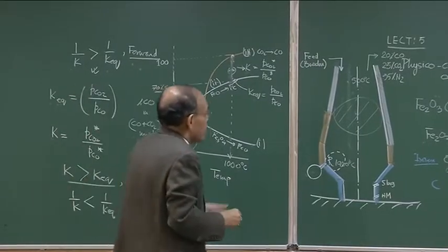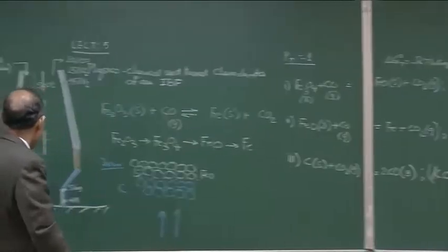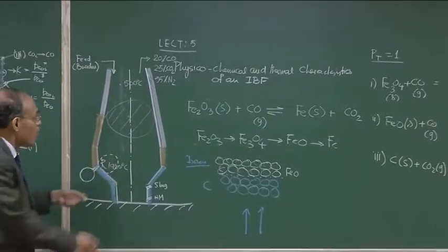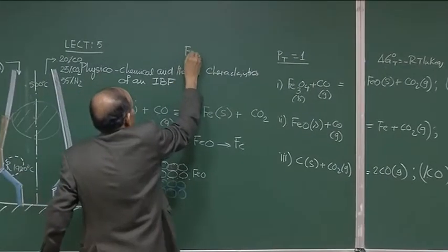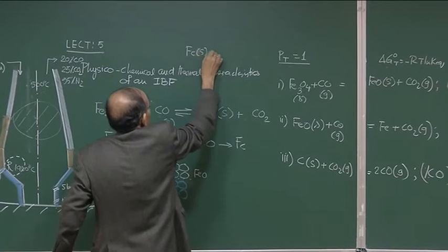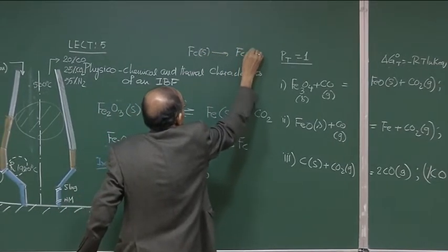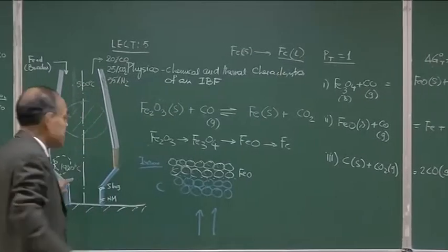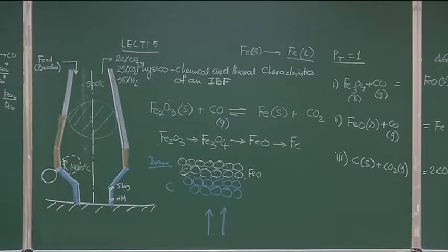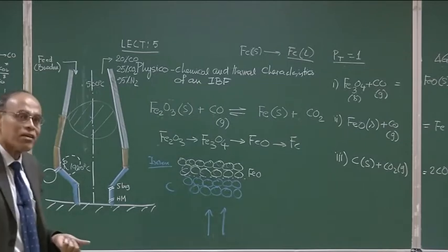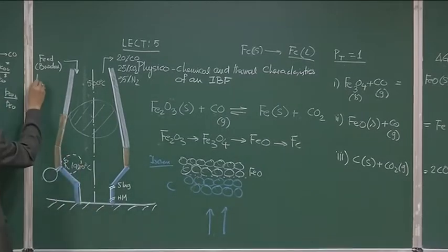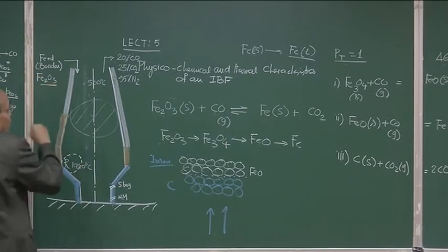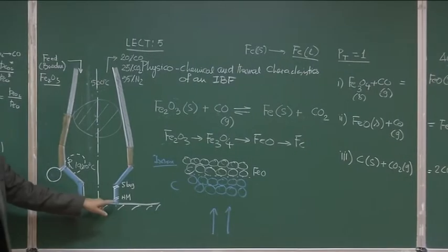Since the temperature is higher towards the lower part, once iron is produced and as the charged material further descends, it is also understood that solid Fe thus produced from iron ore can undergo liquefaction or melting, and gives rise to Fe(L) because of the intensely high temperature which is prevalent. So, conversion of solid iron into liquid iron is also not a limitation. So, the more we charge Fe2O3, there is no doubt that in such a tall shaft furnace we will be getting hot metal in the liquid state, which contains predominantly iron.